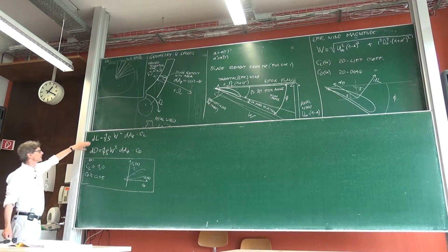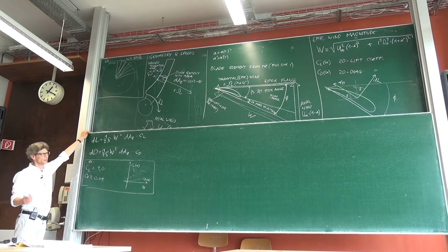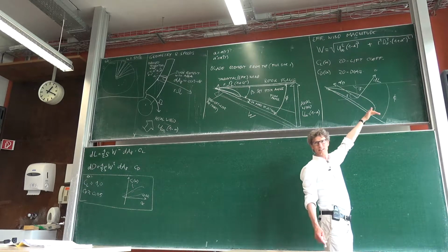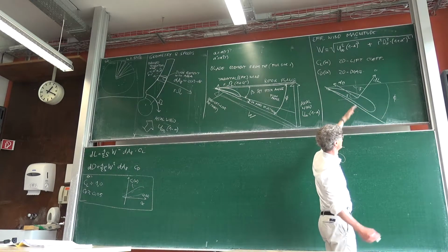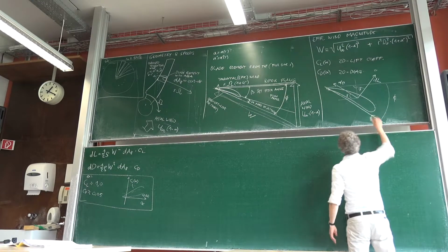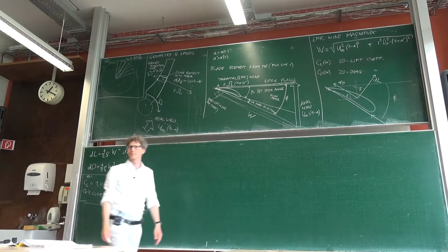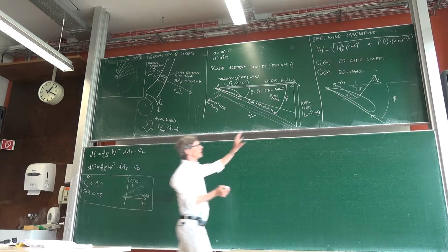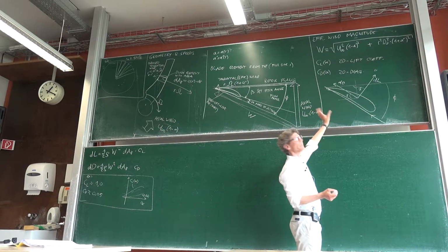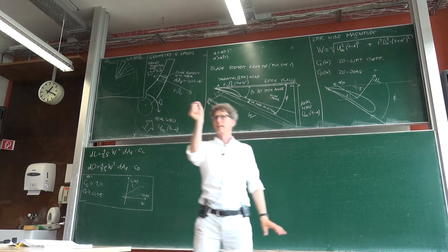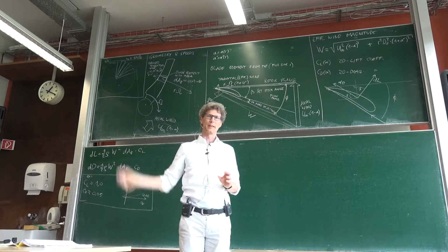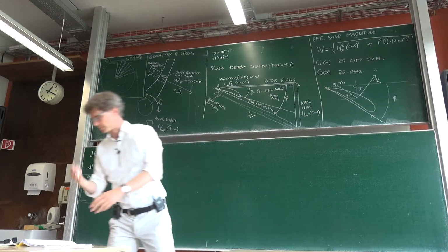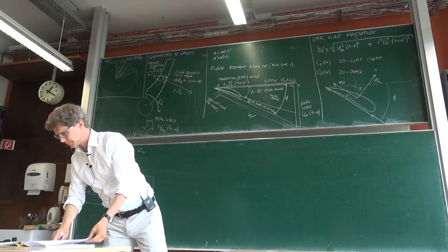So now we have the lift and the drag force, absolute values, and we know that their directions are not aligned with the axial and the tangential coordinate system, right? They are in a different coordinate system, which is imposed by our effective wind. And so now we would need to compute the force that we get on our blade element due to lift and drag in the direction in which we move, which will be the one that gives us power, and in the direction in which we don't move, which will be the one that slows down the wind, right?